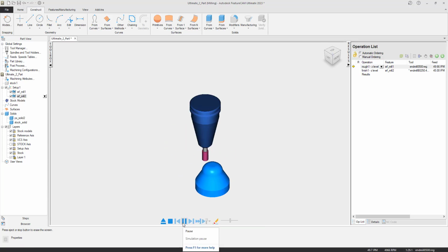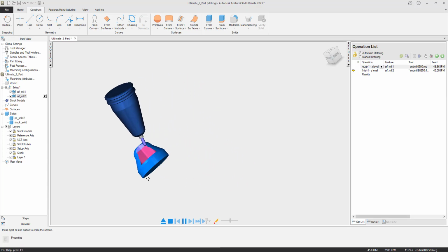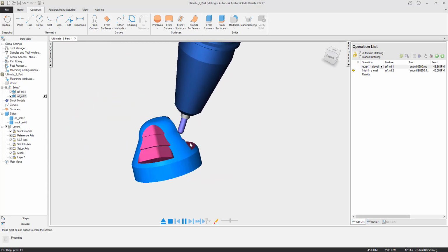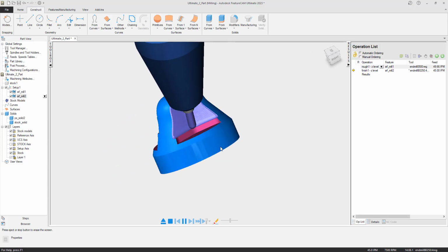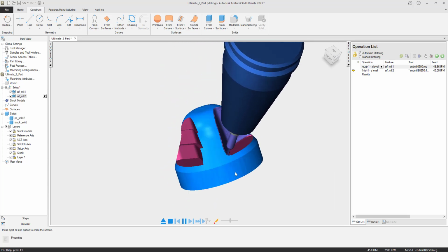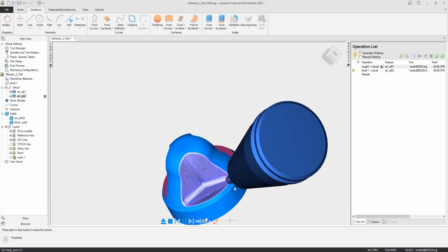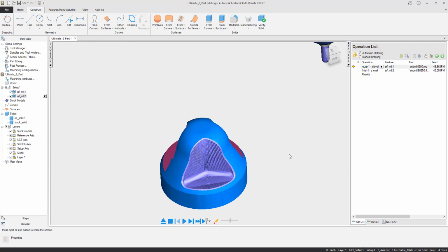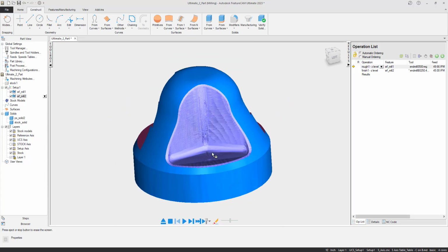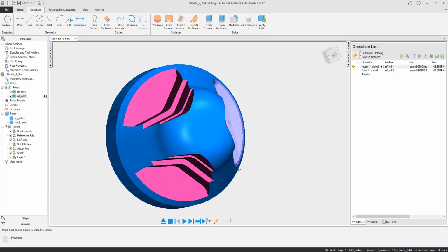I will come back up and go to isometric view, and I will simply hit play one more time. This time, after it gets done with the roughing, you'll see that the way it's leaning is a little bit different, and you'll see that my machine isn't tilting as much to make what it's trying to do. Now you'll see me kind of moving this around. I'm just trying to get a good visual on here, but it's going to be doing the same tool path but with less lean, so that way I'm less likely to run into vises and tooling and fixturing and still get the same results. And looky there, that's really cool. Now that I have good tool path, I've got a good lean, and I'm coming from a centralized location that will work with all 3 pockets.